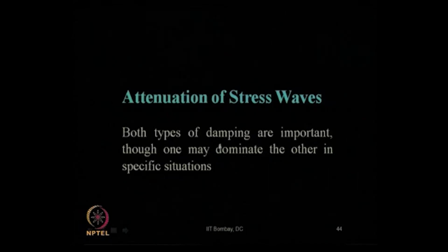In our seismic analysis, in geotechnical earthquake engineering analysis, we will see later on that when we talk about any analysis, many a time researchers consider the viscous damping only, or the material damping only. Many a time researchers forget to take advantage of the radiation damping when the earthquake analysis is done.